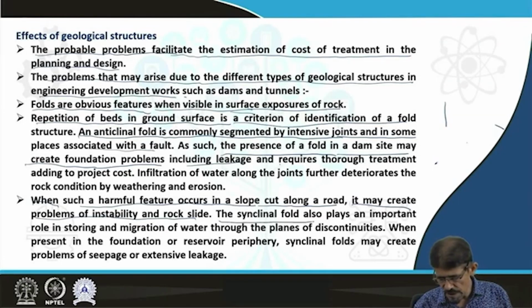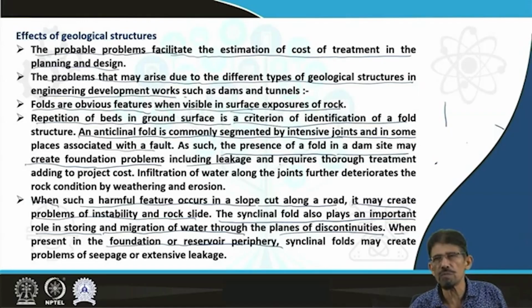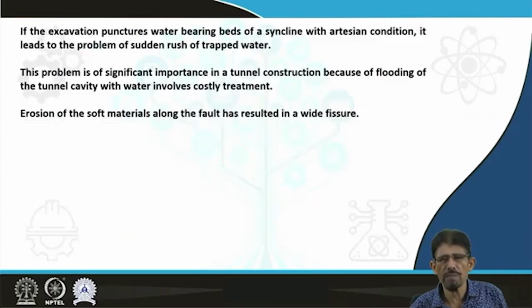Similarly, the synclinal fold also plays an important role in storing and migration of water through the planes of discontinuities or the planes of interface when present in the foundation of dams or reservoir peripheral area. This may also create a lot of problems concerned with seepage and reduction in strength and durability, particularly in the case of an earth dam, where it causes piping and others.